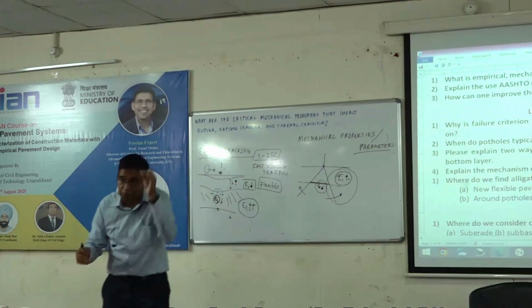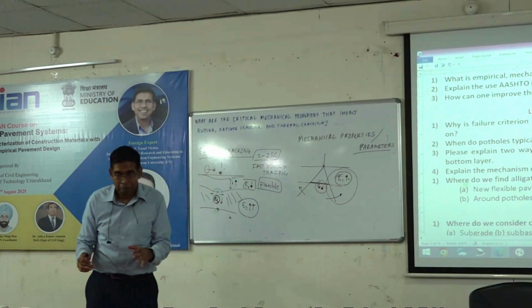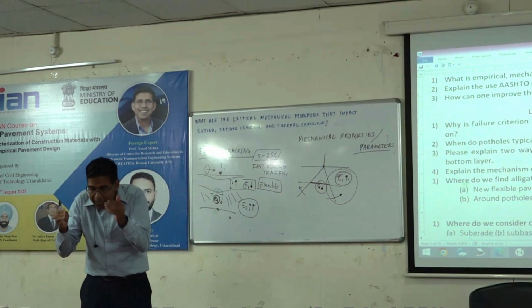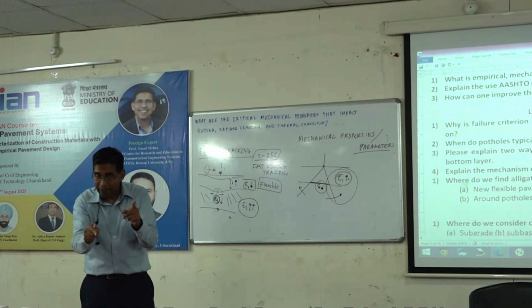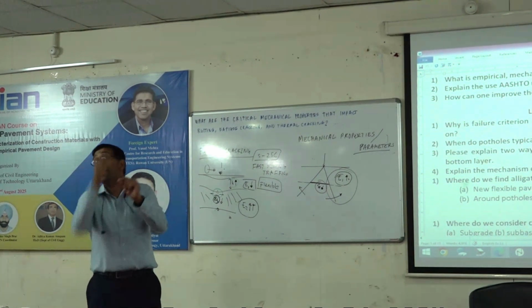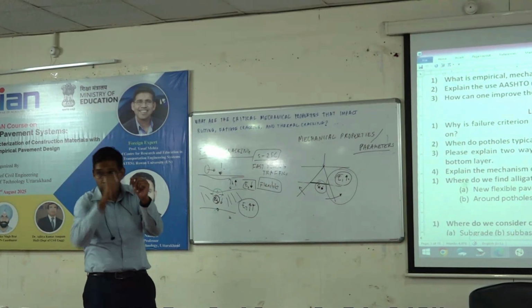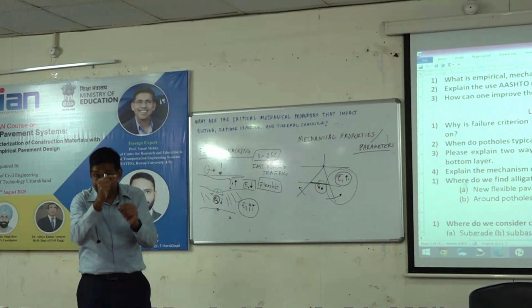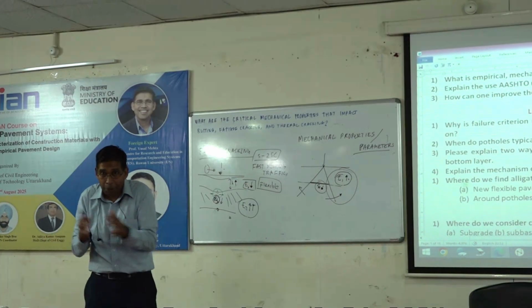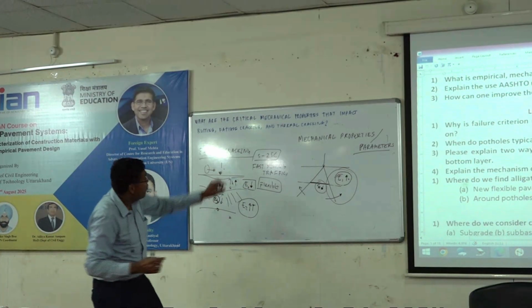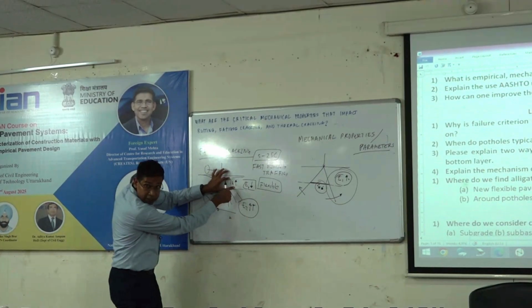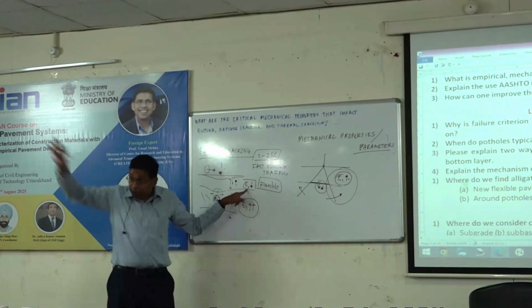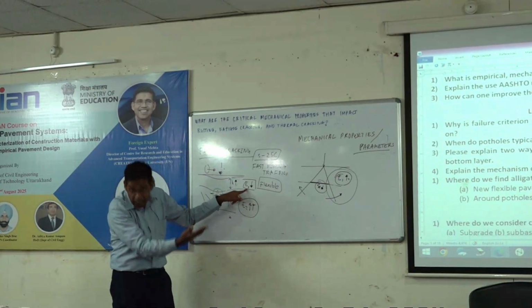This is the concept of optimization of the pavement design. You need to immediately understand, oh, this is the parameter I want to control, number one. And second, what is between that and the load? Between these two, if I can select, I have only a finite number of dollars or rupees, right? Does that make sense? If increasing the thickness is the easiest and cheapest way, I will do that first. But if getting material from far away is more expensive, then I can't do it.